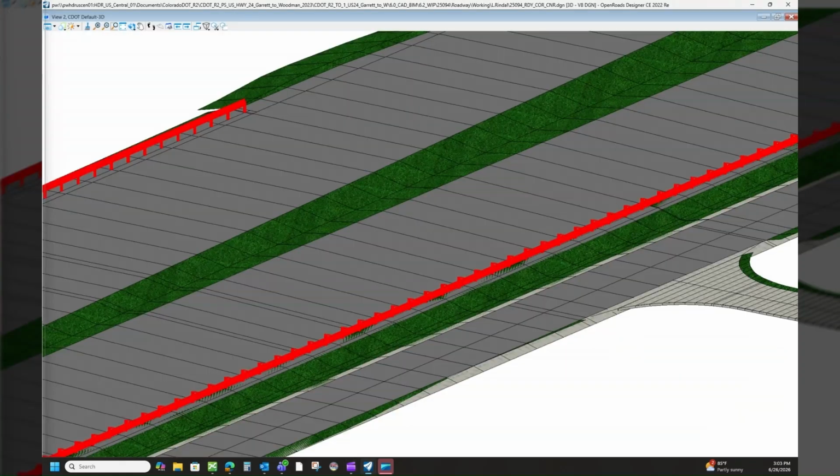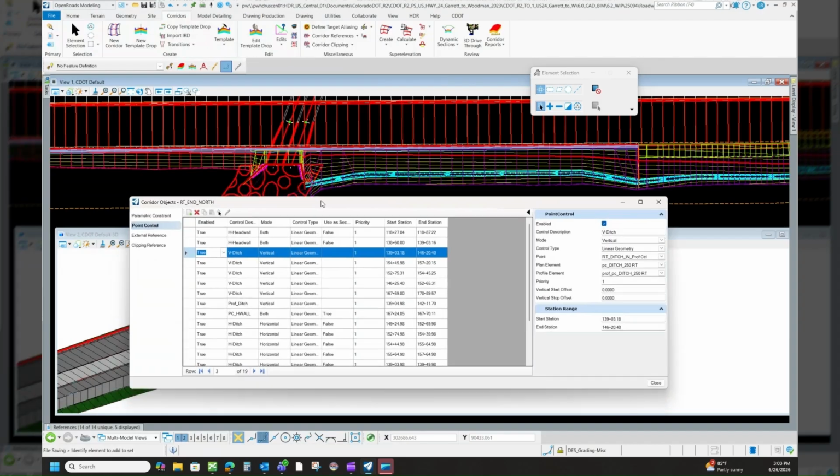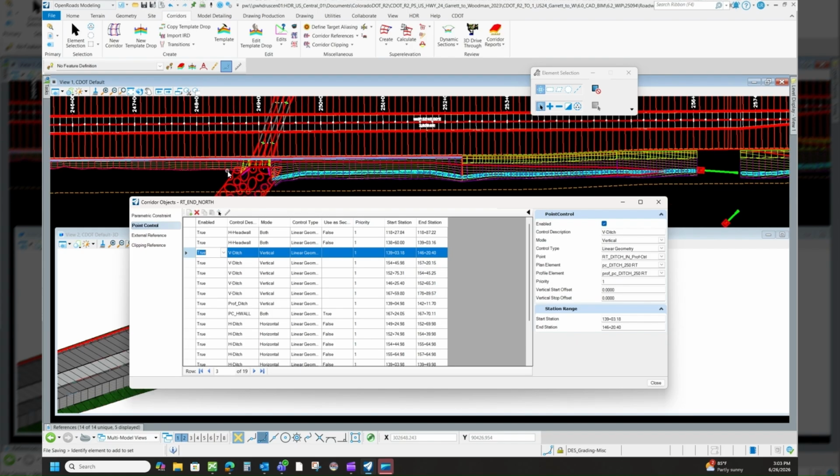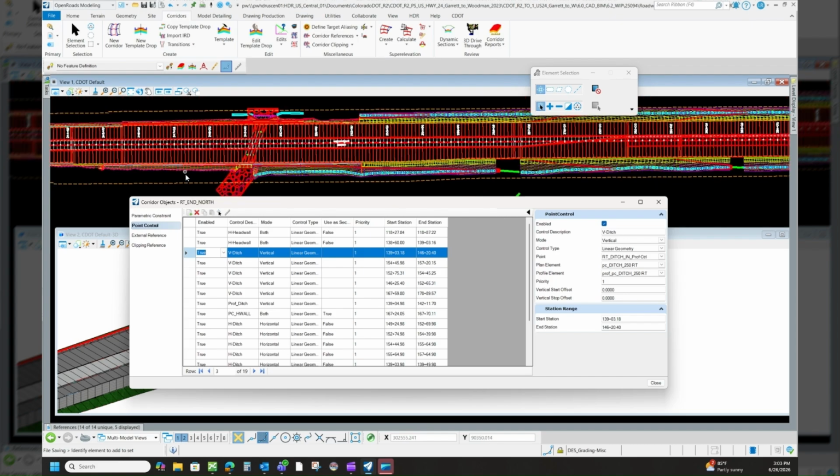Okay, so as you can see, we have quite a bit of controls in here. And one major thing to note, a rule of thumb, is you really don't want more than 25 controls in one file. And that is the reasoning that we split all these up. Now we do have lefts and rights in the same file, which is significant. And I think if we did this over again, we'd probably split them up possibly a little bit more, maybe have the culverts in their own or something. We'd have to go through a whole new digital delivery plan and all of that.